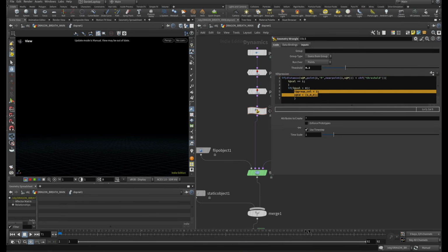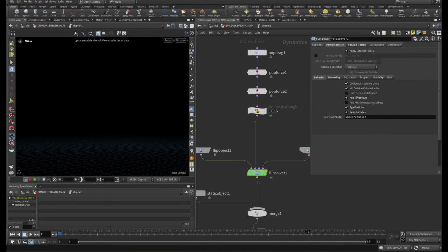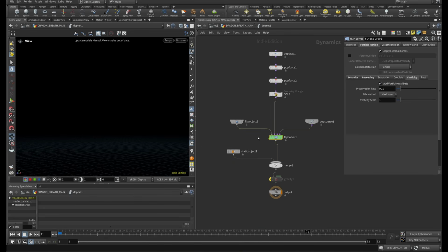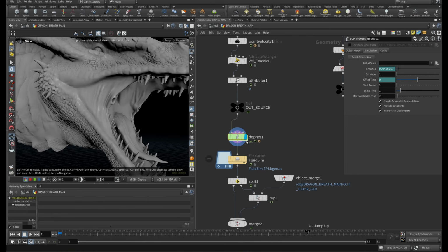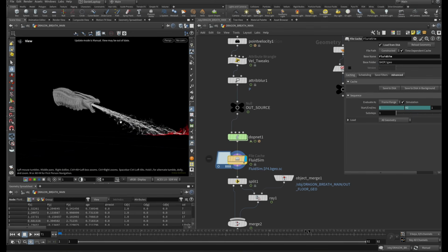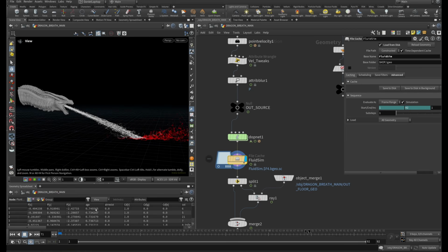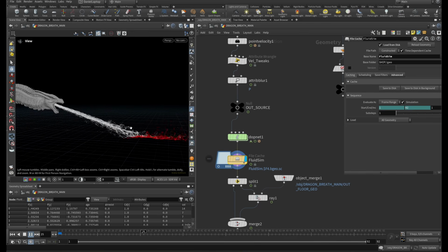You just need to create your flip solver, making sure that you have an ID attribute and that you have your edge particles and rip particles enabled, and that's pretty much it. You need to make sure that you have your environment as a collider, and you will have this very basic sim that, as you are going to see after this, we are going to start tweaking post simulation to have exactly what we want for our emitter.